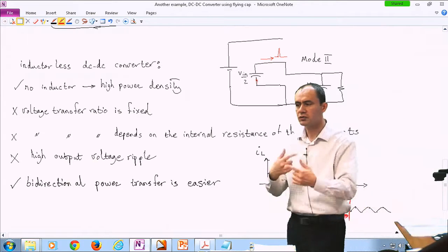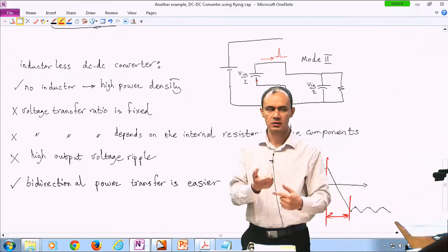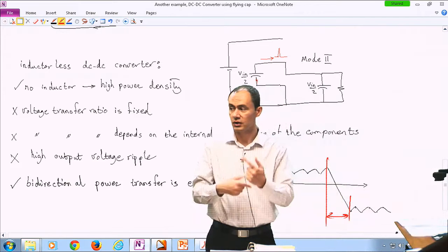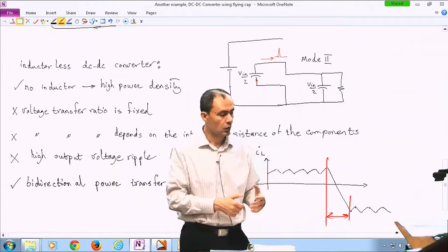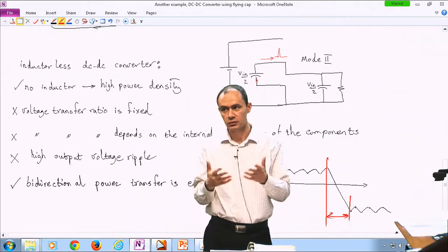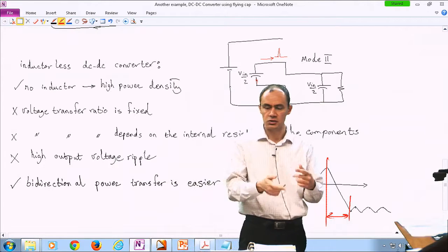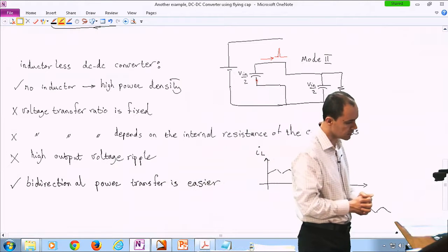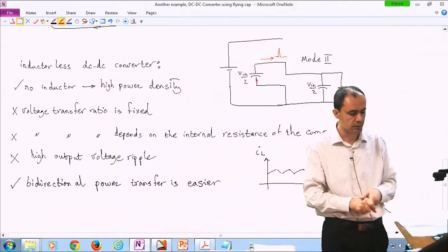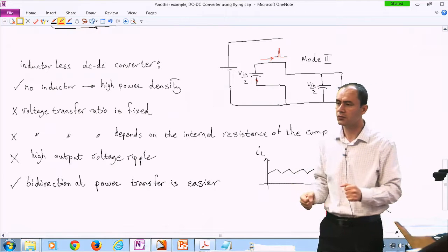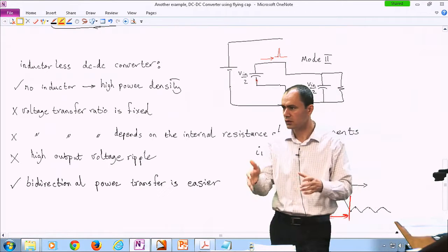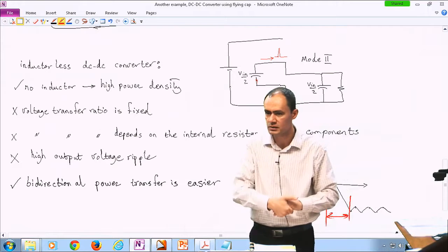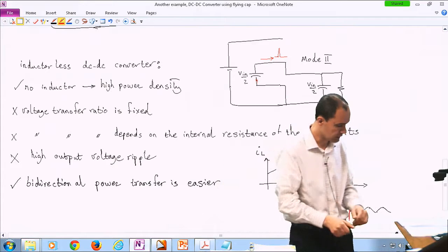to actually reverse the polarity of power, because it takes a while to reverse the direction of the current of your inductor. Over here, there is no inductor, so we don't actually have this limitation. As soon as we modify the switching pattern, you can actually start getting power from your right load or whatever it is and send it to your source, basically. So no delay, basically.